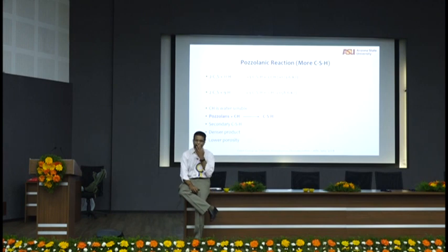So fly ash is actually a good thing. Now, when does fly ash become bad? Is there a situation that you can think where fly ash is not very useful? Coarse fly ash, because they don't react well. Yeah. Why beyond certain limit? Because it doesn't react much. So you won't get CSH.